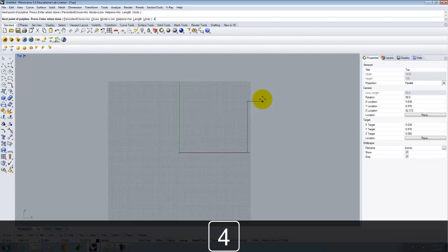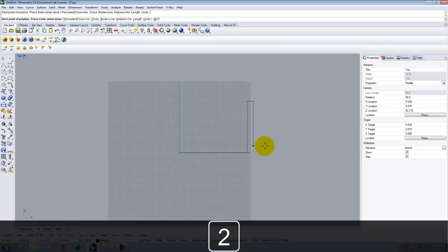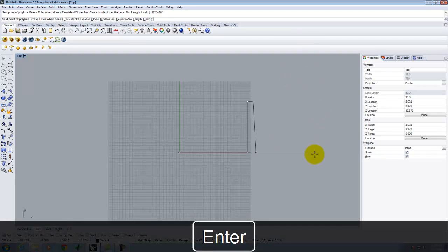The top here is 4 inches. Okay, now here's an interesting one. If we look at the edge of this, it slopes out by 2 inches over the course of the 36 inches. If I want to draw that, it's much harder to type the length. Instead, I would use relative coordinates. This is a perfect opportunity to use relative coordinates. So I'll say @, and I need to specify the x distance first, so it would be 2 inches, comma, the y distance, which would be negative 36. And by doing that, I can get that sloping line.